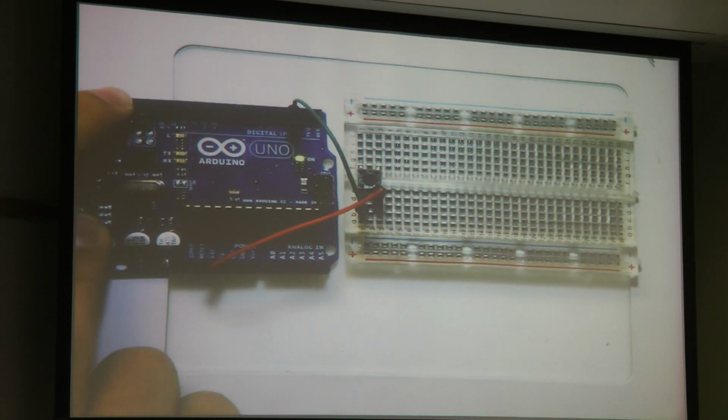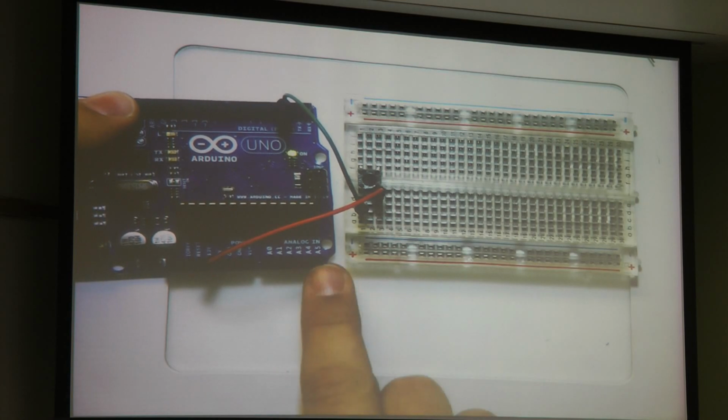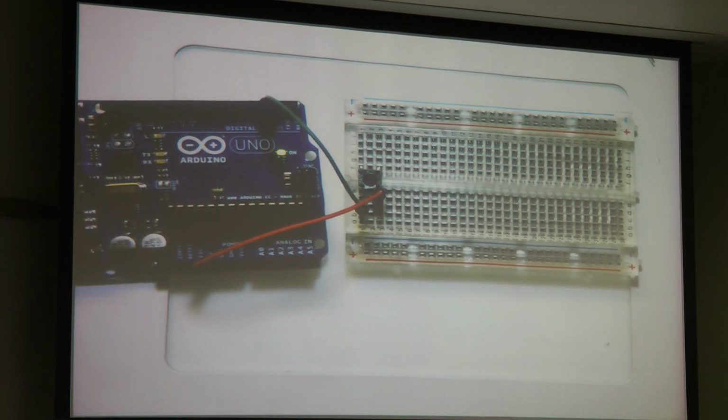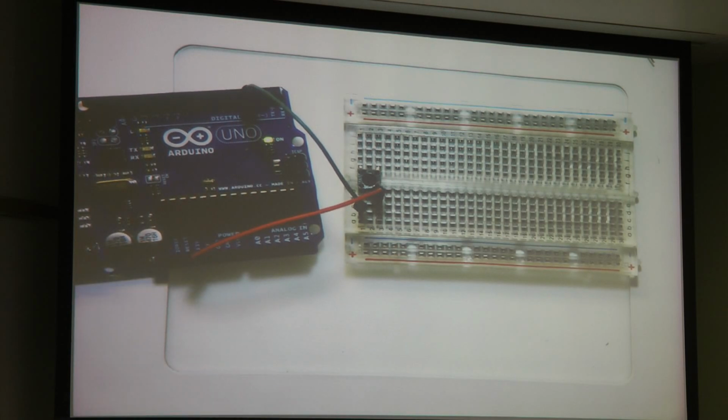They actually added more pins to these headers on the Uno. They have an I2C interface here, which is actually just these analog pins, so don't think you're getting any extra pins. And they have an I/O reference level, which is if your board's like 3.3 volts, if the shield's set up properly, it'll actually change its levels to be at 3.3 volts.